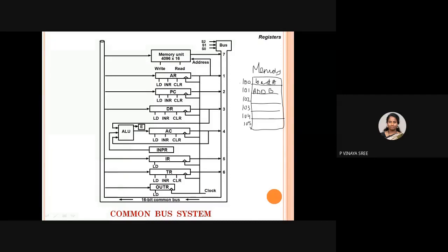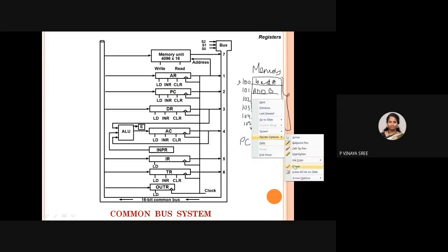First, the processor has to go to this particular address. For that, we are using a register called a program counter. Consider the processor is executing some other task. To execute this set of instructions, we have to place the starting address of this in a program counter. So whatever address we have in memory, called 100, we are storing inside a program counter.